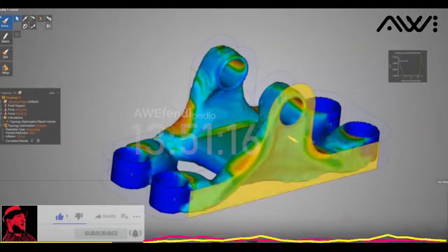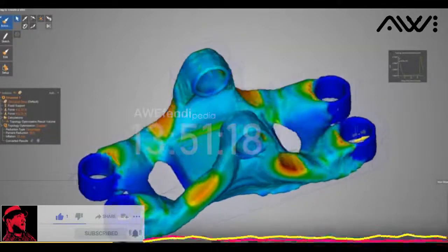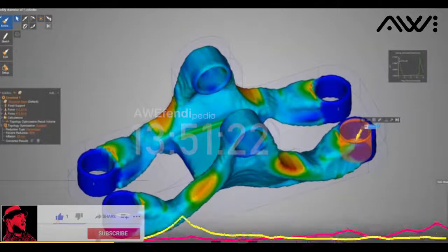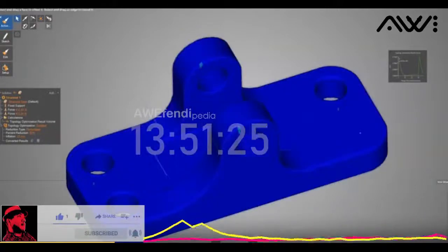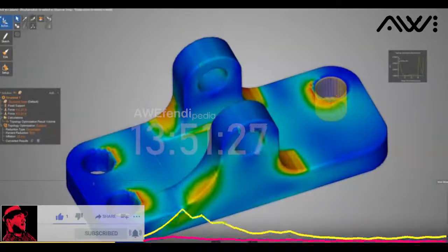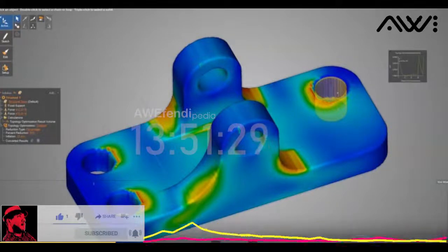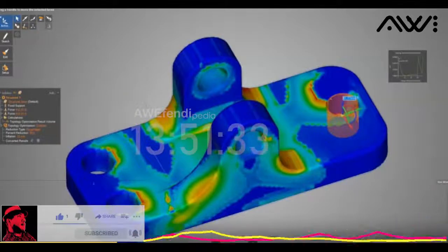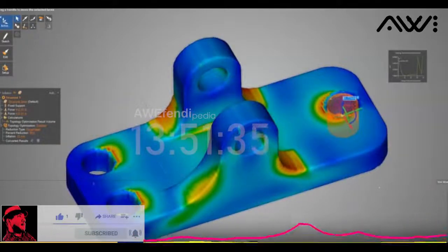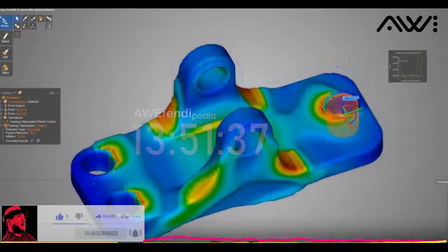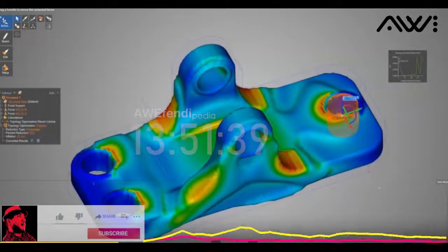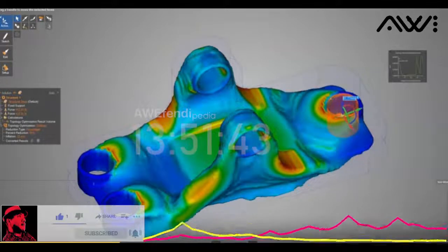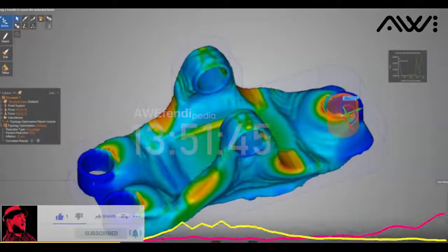Now the other area to think about, as I mentioned, is what happens if we change some of these brackets. I'm not going to mount at 4 areas. I'm just going to come in and delete using the delete command. And then I'm going to move this whole thing, and let's say we move it over to center it a little bit more. I'm now editing in real time, and I'm getting instantaneous results. This is that bullet point I mentioned on the agenda of interactive topology optimization. What if I did this? Or what if I did that? What type of result am I going to get?